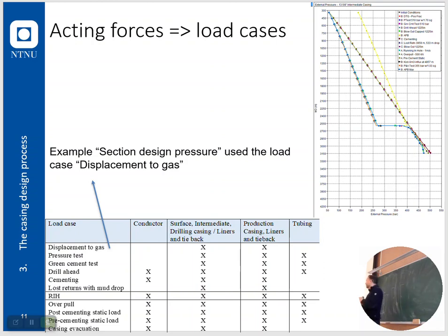So that's why, in many cases, I often tend to forget the connection part of it, because I know they are stronger, right? But that's dangerous. Don't do that. All right, overpull. You need to know the actual stress that you're going to have on the casing as per se, and the casing is able to take that, right? The purely actual pull. And rig for that matter.